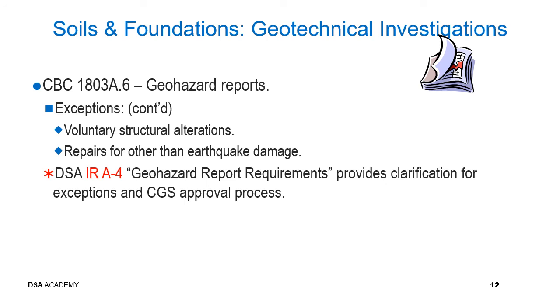And then you need to make the contractor aware until mitigation is complete, they cannot start any foundation work. Very important to understand. And when you have geohazard report, read it thoroughly, see if it requires any mitigation. Usually mitigations are for liquefaction or loose soils deep underneath, which could cause major differential settlement under the building.